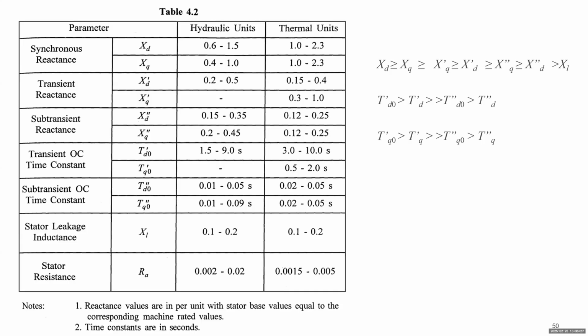You want to add sub-transient or transient dynamics, but you are missing those data. If you have a very classic model, very likely you have this one or maybe that one, but based on this range, you can also create the sub-transient and transient values, like the S double prime or T double prime.